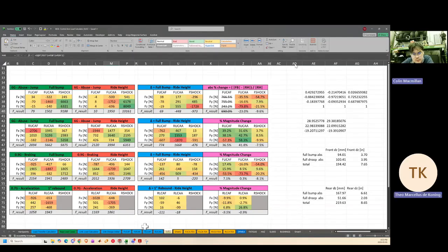We assume ride height, or we assume that full bump would be the worst case usually for most of these situations. For the jumps, yes. In reality, it'd be good to know the actual position of the control arms during a 6G jump. How much do we actually compress the shock? But without that data, I just assumed that it would max them out.